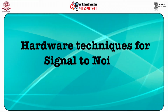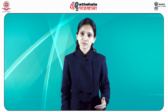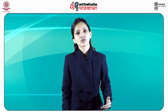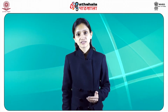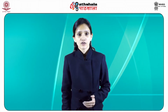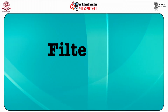Next is hardware techniques for signal to noise enhancement. To avoid losing data, the signal from the input transducer should be sampled at a speed twice that of the highest frequency component of the signal, according to the Nyquist sampling theorem. Adherence to this theorem is significant to obtain dependable results from either hardware or software S/N enhancement methods. First is filtering.